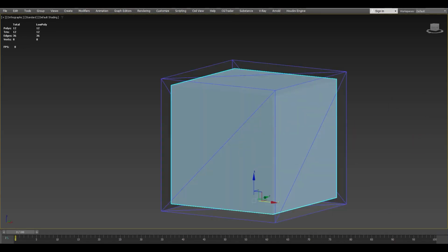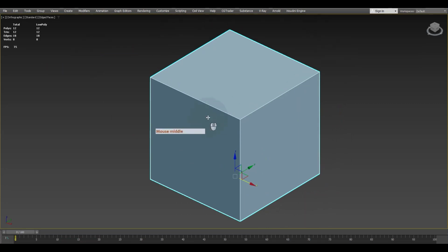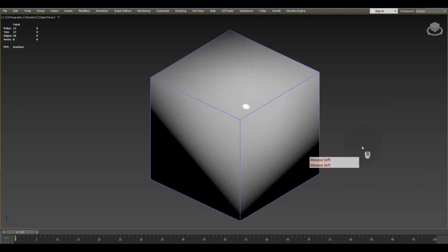On the model, let me show you. Okay, let me delete this. We have this sharp edge, okay, without any transition, any chamfer or anything else. So when we have a sharp edge on the surface, we need to create a UV seam cut here, okay? The other solution for this is removing all the sharp edges, like this, okay?